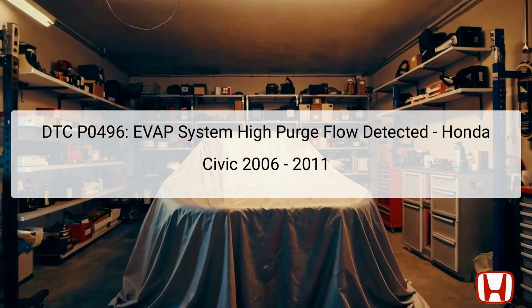The DTC P0496 is specific to the Honda Civic models from 2006 to 2011 and indicates an issue with the evaporation EVAP system, specifically referring to a high purge flow condition. This fault code suggests that there might be excessive vapor flow from the EVAP canister, triggering the vehicle's onboard computer to register an error. The EVAP system is critical in managing fuel vapors from the fuel tank, routing them to the engine to be burned rather than released into the atmosphere.